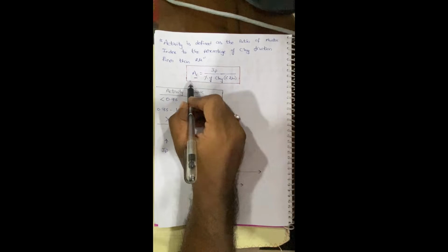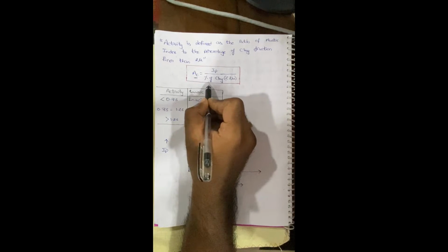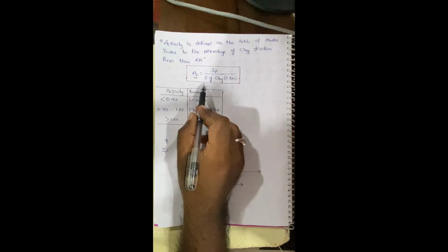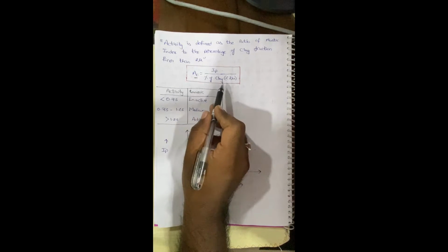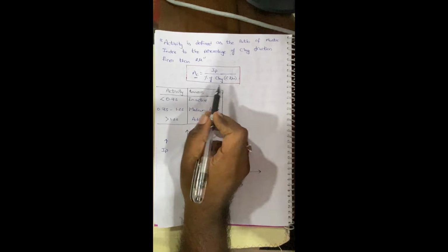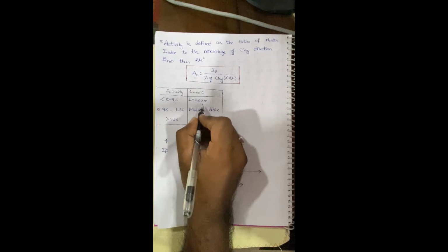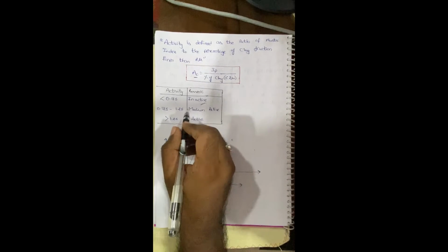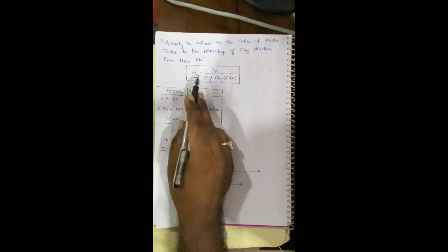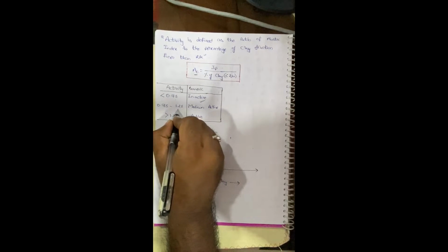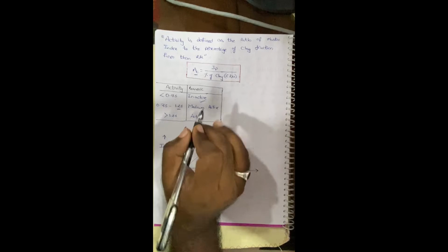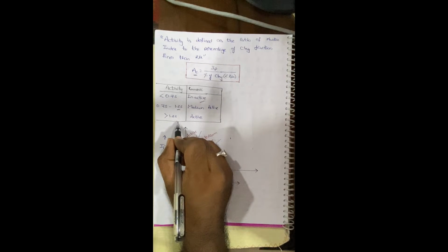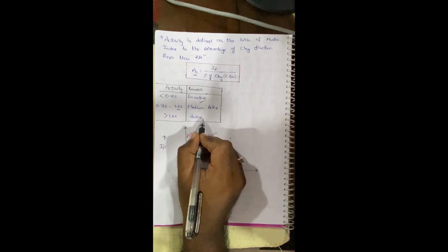If you see the formula, AC is equal to plastic index to the percent of clay which is less than 2 microns. If we calculate the value of activity and we get a value less than 0.75, then it is said to be inactive material, which doesn't show the swelling. I will explain you later. If the value of activity lies between 0.75 and 1.25, then it is medium active material. If the value of activity is greater than 1.25, then it is said to be highly active material.